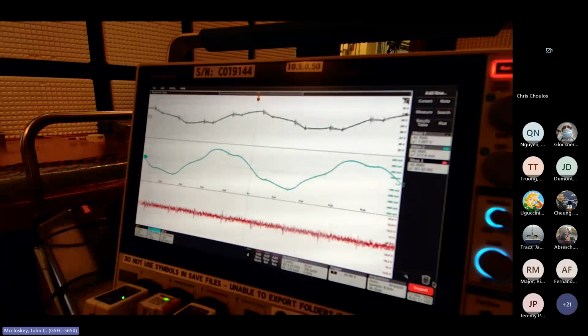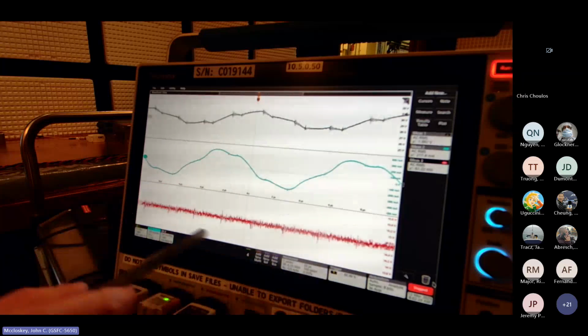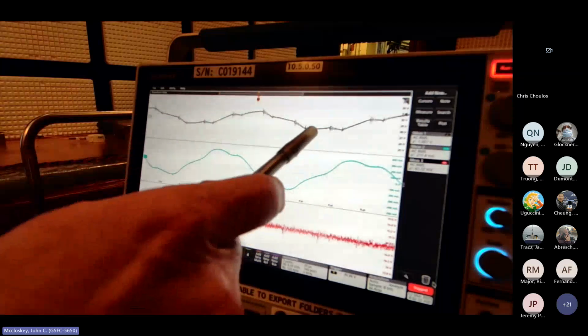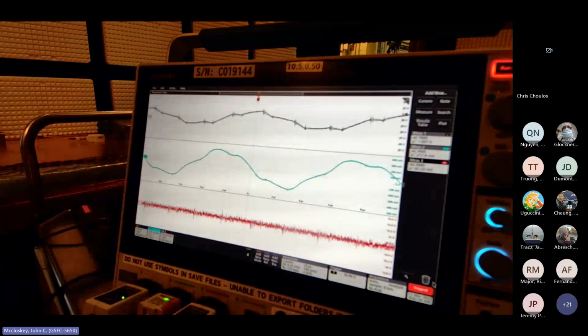That ringing is from the switching action of the power converter. But again, at 100 kilohertz, the sampling of the input waveform, the control loop of the power converter is still working pretty well. You're not really seeing a lot of the 100 kilohertz waveform feeding through.